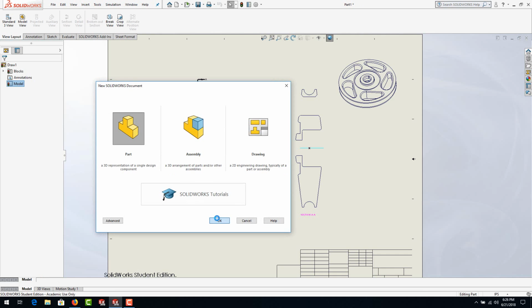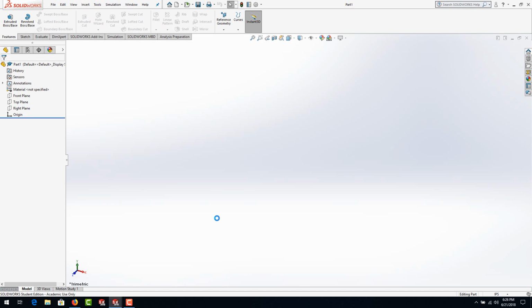And I know what you're thinking. There was an option to import it directly into a part. Be aware, depending upon how many resources your computer has, SolidWorks doesn't always handle a huge file well in a part file, or especially in a sketch. You might have a very large AutoCAD file, and all those lines, all the text, all the geometry, could be a literal mess to have to deal with. That's why the method I'm showing you might be of benefit, especially for large files. I'll show you how to import one directly into a part a little bit later.